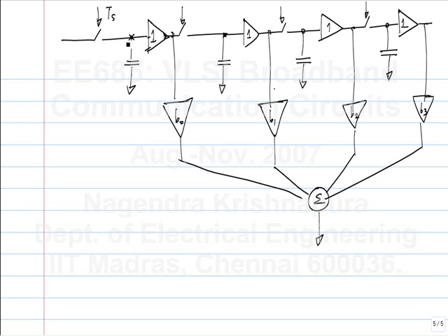So this is one way of implementing a discrete time analog equalizer. We make a sample and hold. The timing is defined by the clock, the sampling instant. If you have a cascade of sample and holds, then the successive sample and holds hold values that are delayed in time by 1 period of the clock. By doing this, we can get an FIR implementation.